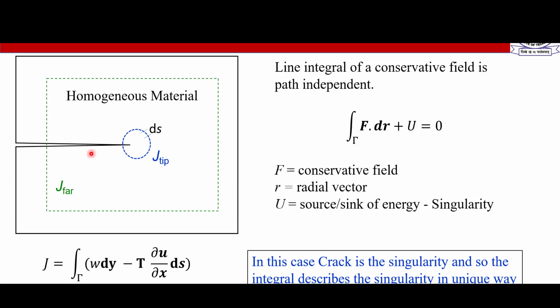So when there is a crack in the system, we want to find out what is the driving force for the crack so that we can manage to understand when a crack will propagate and with what ease it will propagate. So there have been different parameters. For example, in the 20s, Griffith gave his parameter by doing experiments on brittle materials, glass, and he simply examined that the amount of energy which goes in the material must be used somehow to create the new surfaces which form during a crack propagation. So very brittle material will not dissipate energy in the plastic form.